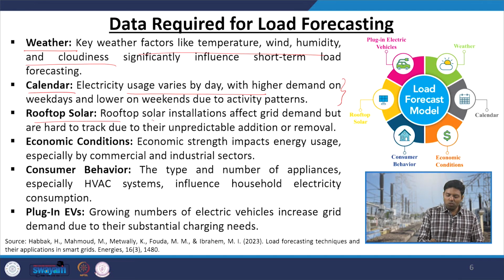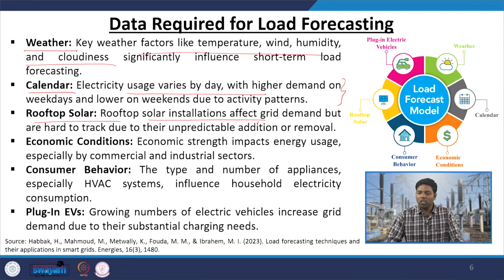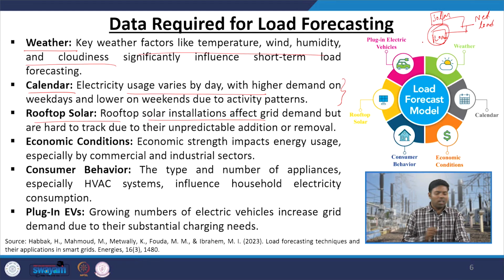You need rooftop solar power generation, because now we have solar power generation in the load. So, if you have solar and then you have load, if you see in the meter, what you will see? It is a net load. So, your actual load is masked behind your solar power.